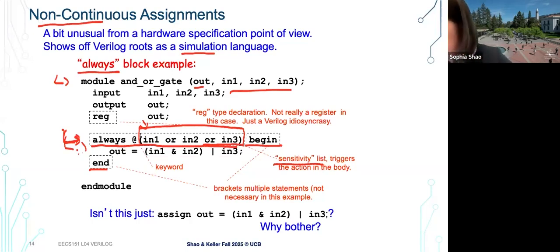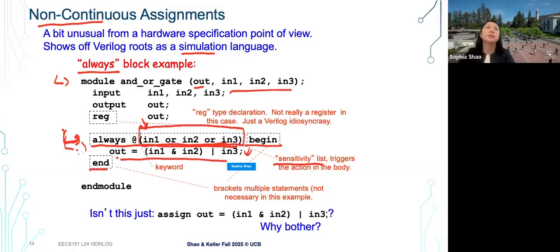So in this particular example, I include all 3 signals. If any of my input signals changes, I enter my always block. And now you will see the semantics are very similar to what we saw earlier, right? It's basically assigning the right-hand side to the left-hand side, right? So let's say if any of my inputs changes, here I'm listing all of the 3 inputs, my output will be updated or propagated accordingly, right?